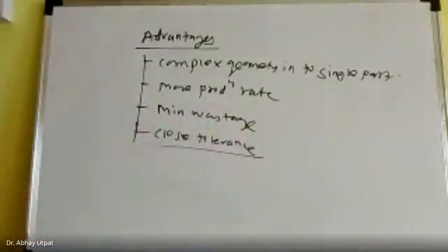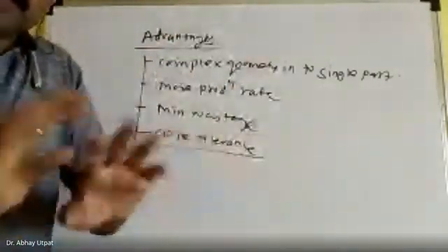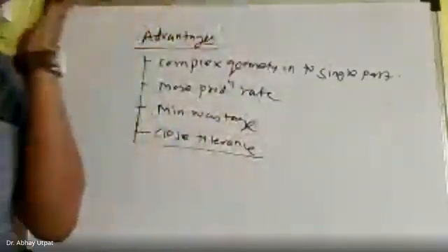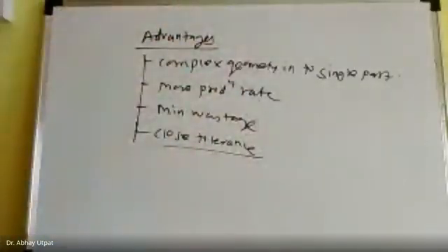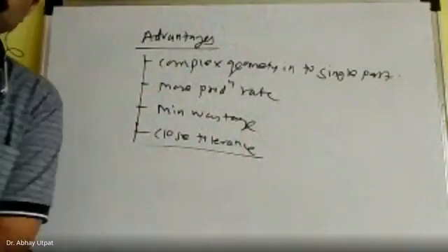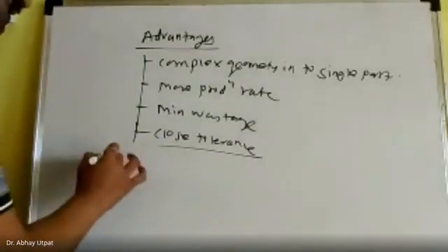Close tolerance is very important because in any of the plastic components, even your chair, there is no second finishing operation on it, within one stroke, because mold steel, P-series, is a type of tool steel we have studied in metallurgy. These are special purpose mold steels which give good tolerance, and hence the products you produce are of good quality in one stroke. Disadvantages are higher tooling cost and setup cost.